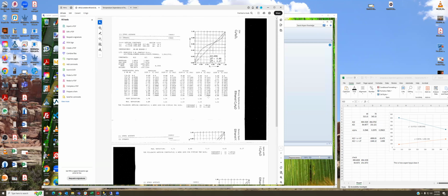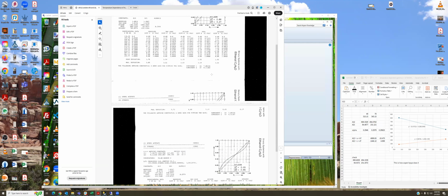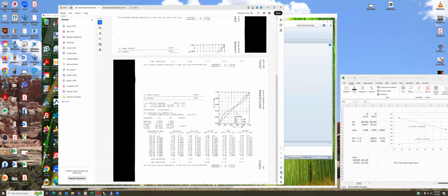So if you look at these data, let's consider that we have a feed of a 50-50 mix of these two components. If we feed that mixture to a column operating at 29 kilopascals, the top stream will be this azeotrope, and the bottom stream will be pure ethanol. Then we take that azeotrope and feed it to a column operating at 96 kilopascals,